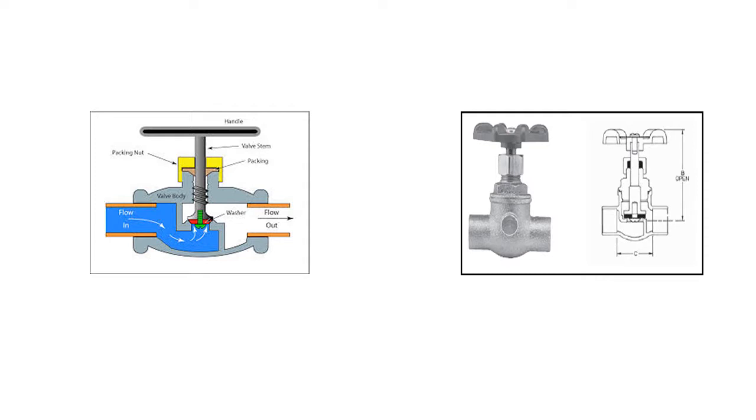Globe valves are normally installed so that the pressure is under the disc. This contributes to easy operation and helps protect the valve's packing. For applications with high temperature steam, globe valves are installed so that the pressure is above the disc. Otherwise, the stem will contract upon cooling and tend to lift the disc off the seat.